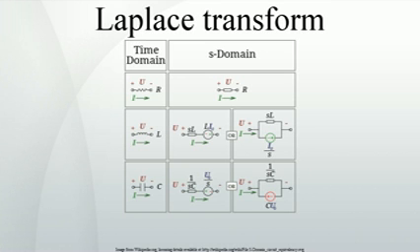In engineering applications, a function corresponding to a linear time-invariant (LTI) system is stable if every bounded input produces a bounded output. This is equivalent to the absolute convergence of the Laplace transform of the impulse response function in the region Re(s) ≥ 0. As a result, LTI systems are stable provided the poles of the Laplace transform of the impulse response function have negative real part.